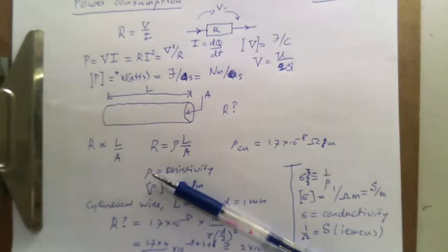So for instance, there's this very famous standard called the Platinum 100 standard, which is a resistor made of platinum. You start with a resistance of 100 ohms, and the temperature dependence has been calibrated super well. So you just stick that in whatever you're trying to cool down. You measure the resistance. You know what the temperature is. So that's a whole field unto itself. If you want to know more about that, take a course in solid state physics, for instance. For the physics majors, there's a 400 level class for that. All right.